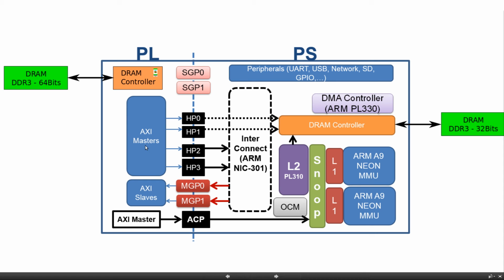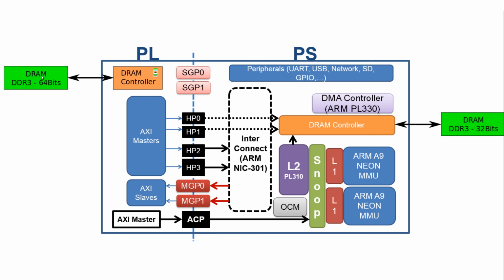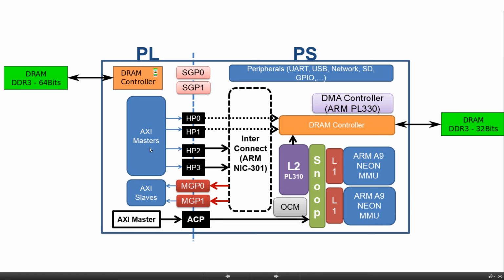Maybe it makes sense to have a separate DRAM channel and a separate DRAM controller directly on the ZYNQ PL, and then to connect this DRAM controller to an off-chip DRAM memory, for example a DRAM module, and then to provide enough bandwidth and space for the accelerators to use this memory for the specific processing purpose. This is what the ZC706 board provides.